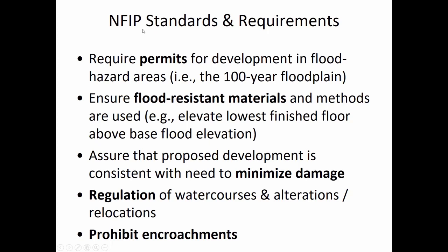The National Flood Insurance Program also is supposed to encourage the use of flood-resistant materials for building, and you do see this more than used to be the case. There are a number of new condos and multifamily homes being built, I've noticed in Milton, where they have a garage underneath, and all of the living space is up above a pretty tall garage. The reason for that is that the garage is just full of cinder block construction. It's relatively flood resistant. They're not putting in a lot of drywall, and they're not keeping the furnishings down below, so that if the water level does rise, they can hopefully move the vehicles to higher ground, but the habitable section of the structure is above the base flood elevation.